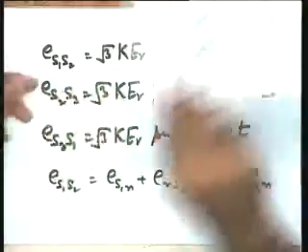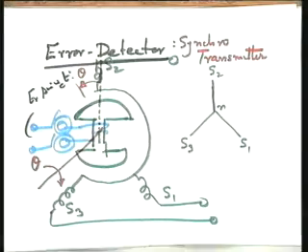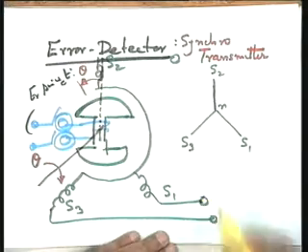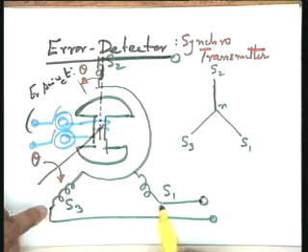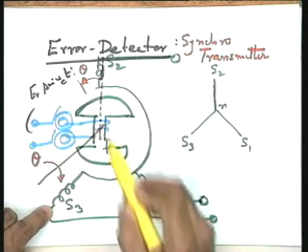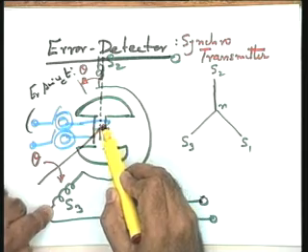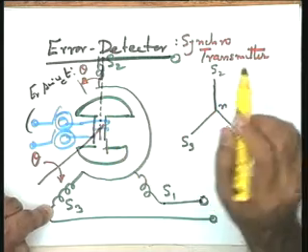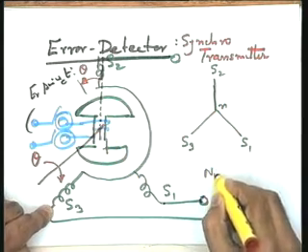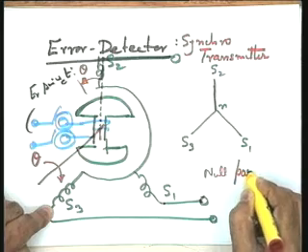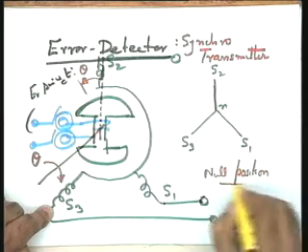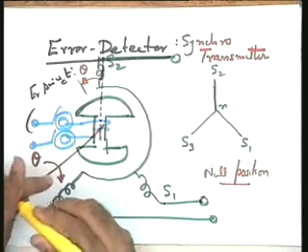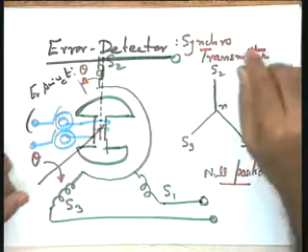Okay? So this particular position, I give you a definition over here. When the voltage across ES1S3 is equal to 0, the corresponding position of the rotor is called its null position, and your theta is equal to 0 reference is given by this null position. This you are going to conduct as an experiment also in the lab.